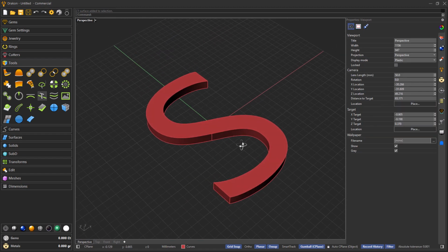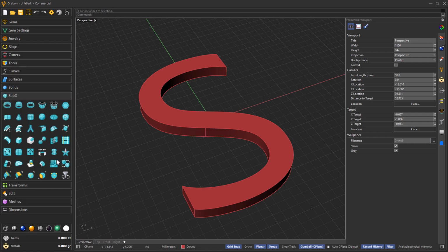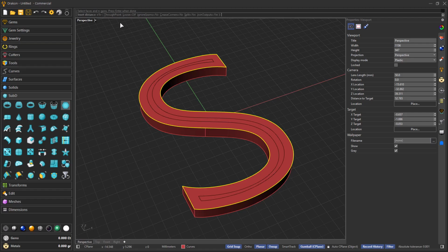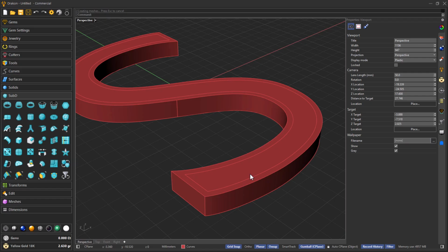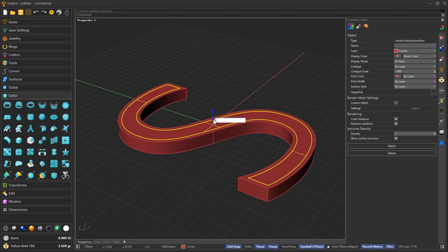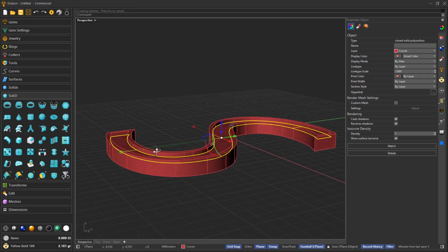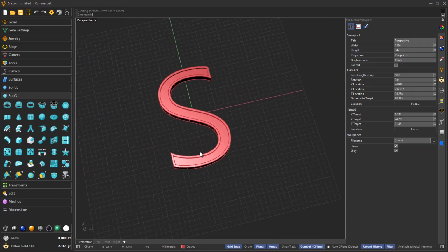So now I want to create on the top area the space for the gems, where I will need to create an inset first. So I will select the surface. Now the distance, let's type 0.4, okay. And once we have our border distance defined, I can use minus 0.4 extrusion distance. So we are having a recessed area with a 0.5 millimeters depth.